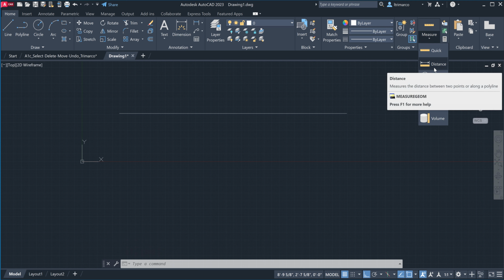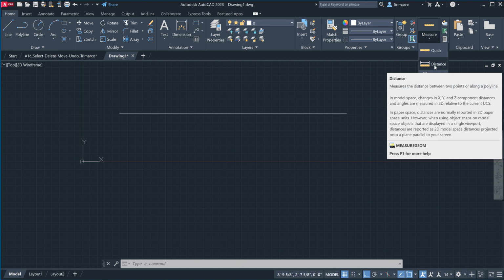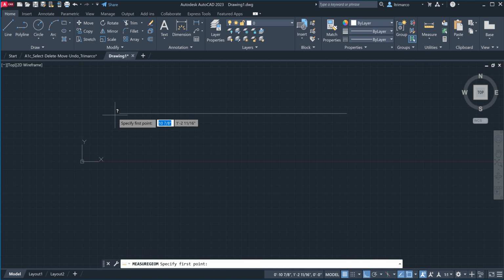And if I want to double check what I've drawn, distance it, if you will, select it and move to one of the endpoints, which again is an object snap tool that we're going to use, and we're going to draw from endpoint to endpoint. It's not about drawing, it's basically snapping to where I want a specific distance to be told. And I know now from this temporary dimension being shown at the top that truly this line is drawn properly at 6'3", and I'm good to go.